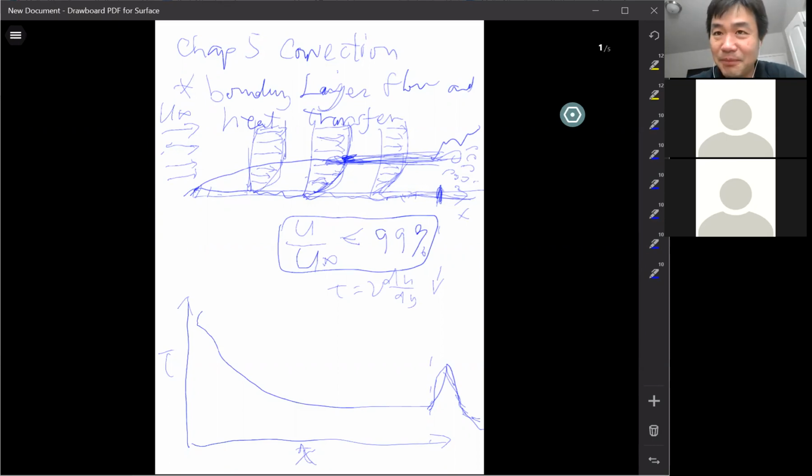When you have a dimpled golf ball, the flow around the golf ball when it flies is more turbulent than around a smooth golf ball. Turbulence gives you small eddies. Instead of laminar flow with a bigger vortex in the wake, which leads to more drag and more shear, the size of the turbulent eddy is basically dictated by the structures, the dimples. So the size of those turbulent eddies is very small, so there are a lot of vortices, but with smaller strengths.